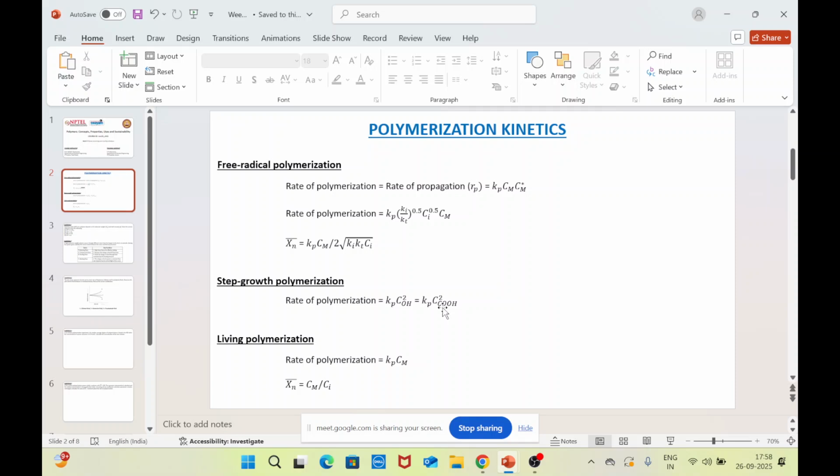The faster the screw rotates, the pace at which the polymer pellet is heated up and forced through the die is going to increase. Next is the viscous heat dissipated. Third is fiber breakage. Because of the shearing action between the molten polymer and the solid pellet, there are chances that the fibers will tend to break. After this, you have the die opening.